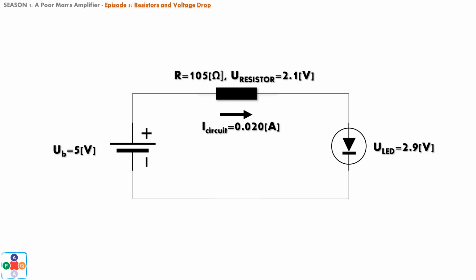When determining and calculating the value of resistor for our circuit, the first guiding principle was the desired current we wanted to run through our circuit. We obtained that value from LED specifications. After that, we needed to choose appropriate power source. Power source must generate voltage that is at least equal or preferably higher than one that develops as potential difference across terminals of LED diode. That potential difference is denoted in LED specifications as forward voltage, and in general, in electric circuits is referred to as voltage drop. After that, by using Ohm's law, we calculated the required resistance for our resistor.